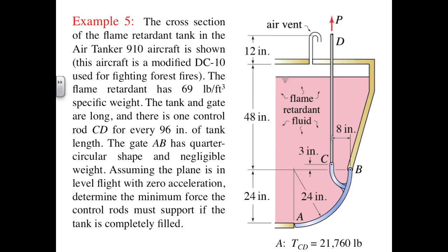If we are pumping the fluid into the compartment and can exert some overpressure beyond atmospheric pressure, then we might be able to fill it up a little further, up to the top of the lower U of the air vent. This requires an overpressure of the specific weight, 69 pounds per cubic foot, times the depth, 1 foot, and converted into PSI, that turns out to be about half of a PSI.